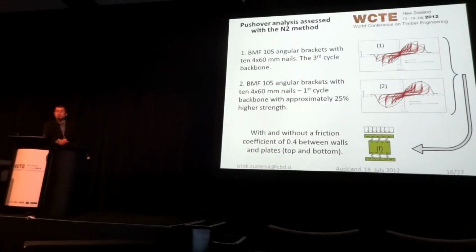Let's just focus on the last line of the table. This is the maximum ground acceleration that we've come up with from our nonlinear analysis, and it's divided by the 0.25 we're using at the beginning for the linear elastic analysis. So in a way, this is a simplified version of the reduction factor, the Q factor or the R factor. And the values we've come up with were between 2.1 and 2.44.